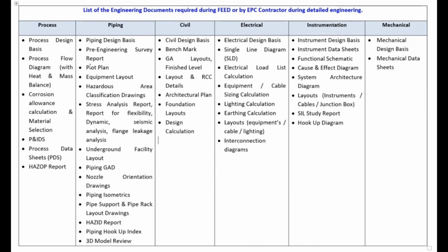Now, after plot plan is developed, then it comes to the equipment layout. See, in the plot plan, you highlight compressor area as one box, okay? Say, in the total footprint of 300 by 300 meter, your compressor area is maybe a 25 meter by 25 meter box in the plot plan. Now, in equipment layout, you develop those individual blocks in detail. Now you'll be developing another equipment layout for the compressor area. So in that 25 meter by 25 meter, you'll be showing that you are putting 3 compressors there, correct? So this is how the equipment layout works.